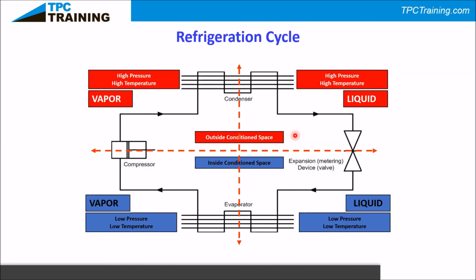But one of the key things I want to end on is that there's no drop-in replacement. So if you go from R22 and you want to change a system out to R410A, there's some adjustments you need to do. Same thing if you're going from R22 to R407C. It's still air conditioning refrigerant, but there's some changes you need to make in the system in order for it to operate properly. Ryan, was there anything else then, sir?